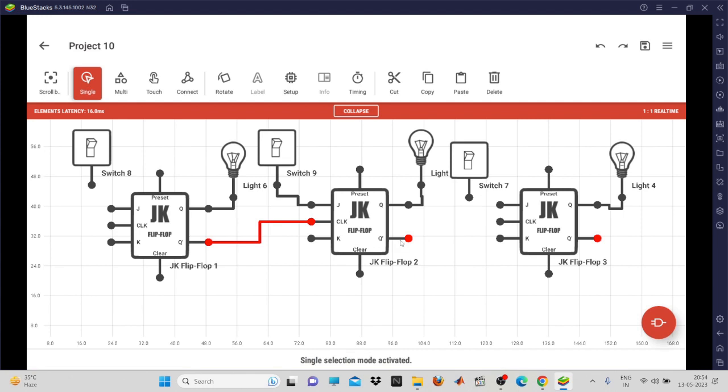Okay, again, right. Now what about the inputs? There is one condition in the truth table that when J equals K equals 1, and if you are providing a clock, then the output is going to toggle. Now, what do you mean by toggle?